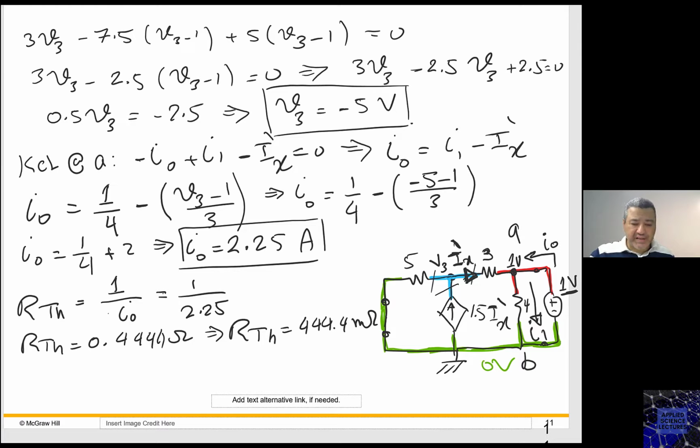The second case is where we have a mix of dependent and independent sources. In this case, we cannot find our Thevenin by only switching off independent sources because dependent sources are going to stay there. They're not going to be switched off. So we have to put a source at the output and then calculate the other quantity withdrawn from that source. And then the ratio between the voltage and the current for that source that we added would be our Thevenin.